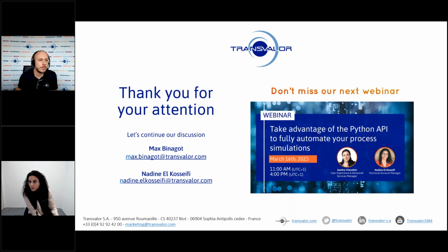There is no time parameter, so how can static and metadynamic recrystallization be managed? To use dynamics for this kind of simulation, we need special material files. Everything is defined in these material files. Transvalor provides some material files for recrystallization. If you do not find your material, we can also send you an identification parameter procedure to find your own parameters for your steel alloy and so on.